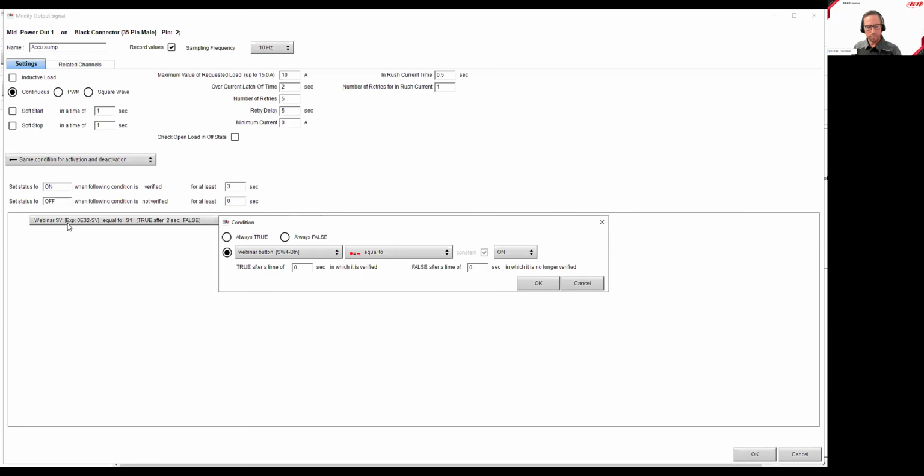I have an on activation that is momentary when I press the button, and then a toggled event. So I can actually say if I press this button, I want it to flash my headlights for as long as I hold it, but it also activates my siren, which is driven by the toggling mechanism for the SW4 and the EPM. So now I have two outputs that are using two different variables, but they all come from the same user input. So the customer just hits the button once, holds it if he wants to flash his lights, but his siren kicks on immediately and stays on until he presses the button again.